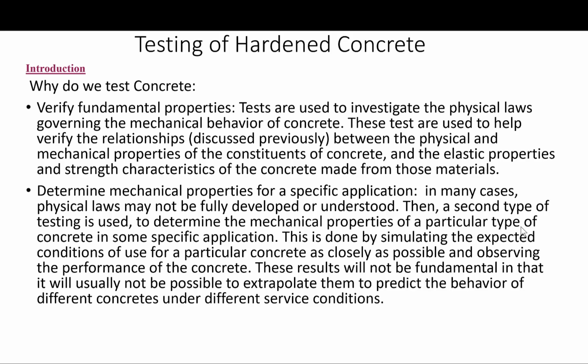Second, often these physical laws may not be fully developed or understood. In this case, a second type of testing is used to determine the mechanical properties of a particular type of concrete in some specific applications. This is basically done by simulating the expected conditions of use for a particular concrete as closely as possible and observing the performance of the concrete.